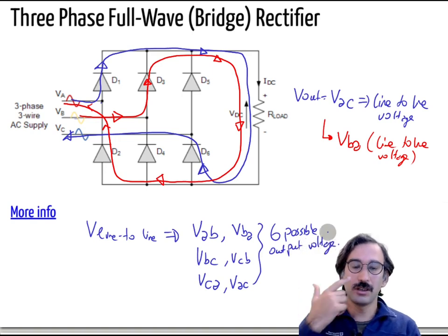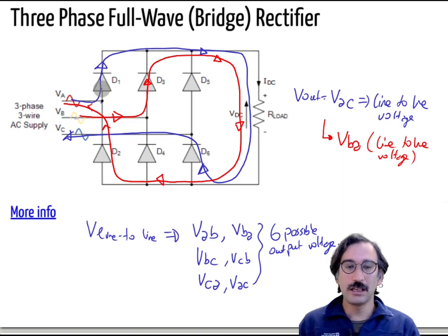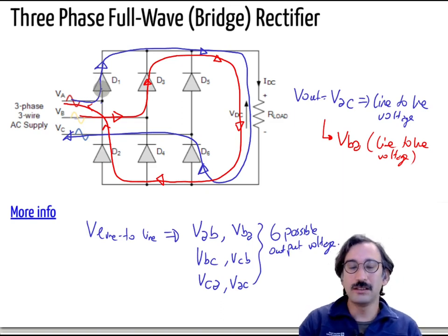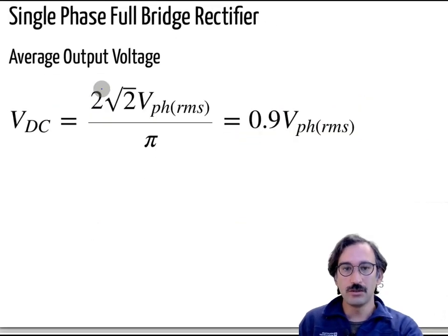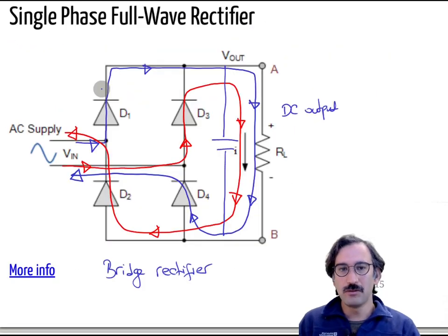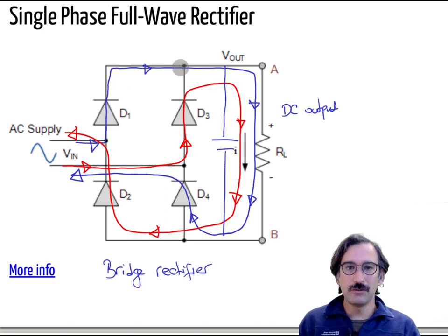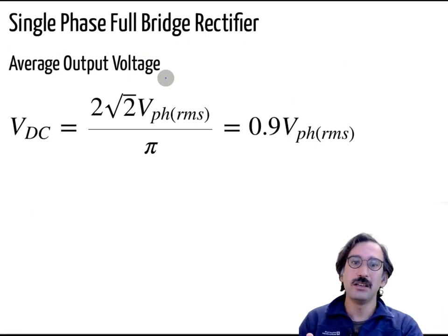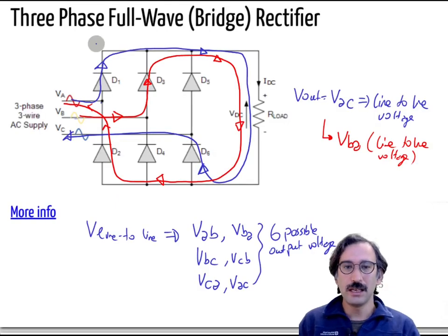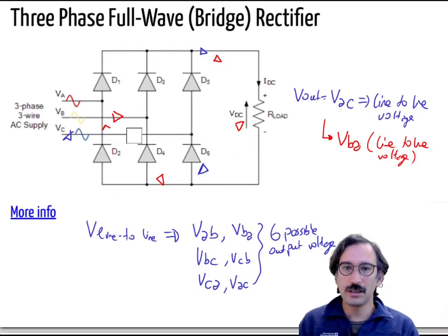Whichever conducts, how can you decide which one is going to connect, or how the diodes decide to get into conduction mode or not? It was happening the same here. For example, if the voltage here is higher at the positive or negative, then the diode gets into conduction. The diode with the highest potential will block the other. So let me clean those things a little bit. It will happen exactly the same.